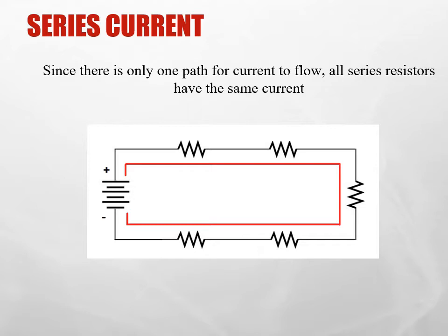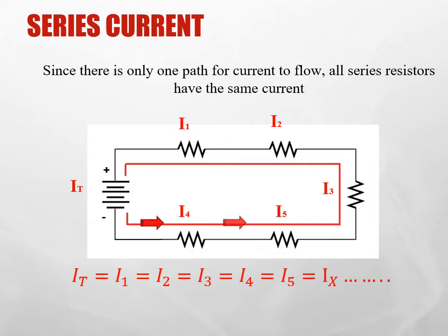Here we have a conductive path, or a closed circuit, going, in this case with electron flow, from the negative of the power supply to the positive of the power supply. Since the conductor medium, or the circuit, is full of electrons, as you put one electron into the circuit, it pushes all the rest in front of it around, so that when one electron goes in, one comes out immediately, because it pushes the entire length of electrons along the conductive path. Thus, the current is the same throughout the entire circuit.